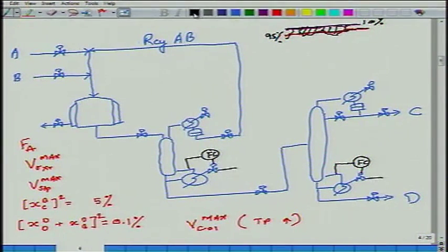What color is this? Black, okay. Maybe this is what I do. I control a stripping a rectifying tray temperature. I control a rectifying tray temperature using the reflux, okay, and this tray temperature set point is coming from a product quality measurement, product impurity measurement.